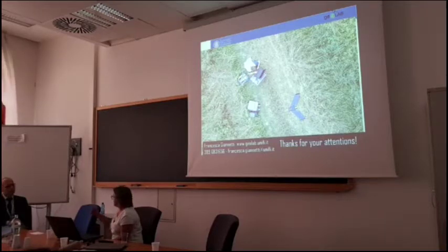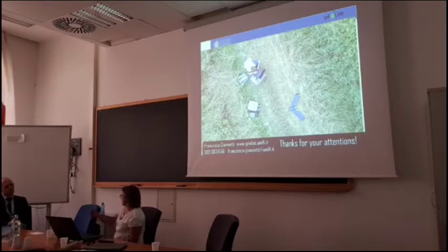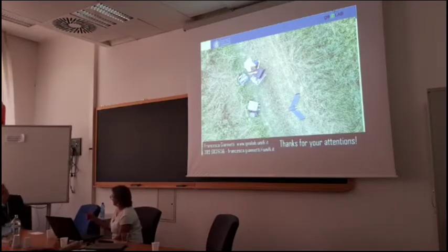Yes, we had some measures on the ground control points with two different GNSS systems, and we saw that usually the authority has 1-2 meters of error on the border, while with some points measured with the topographic double-frequency GNSS, we have a really small error. It's 10 centimeters, which in forest is a normal error. 10 centimeters is nothing in forest. For topographic, it's really different.